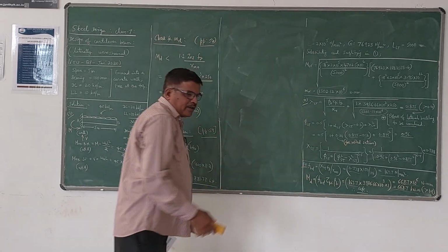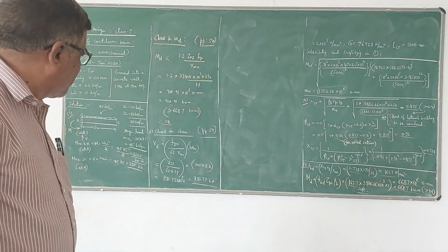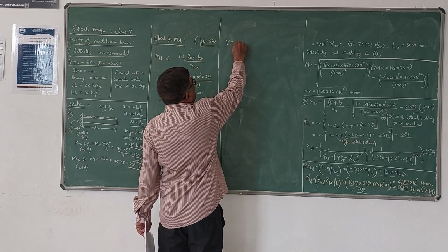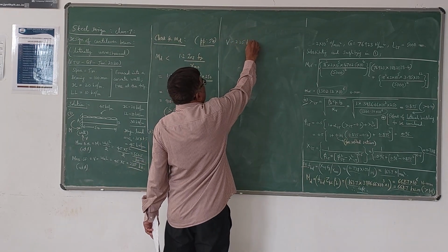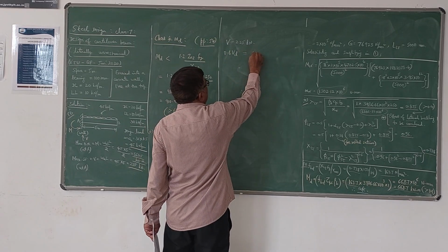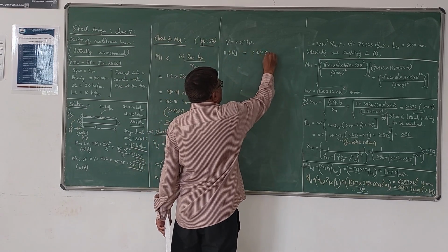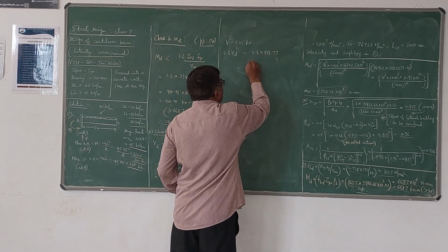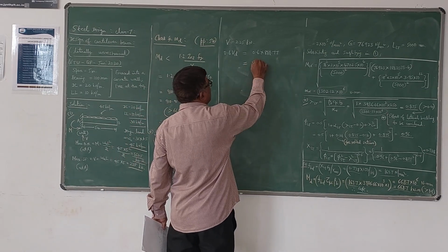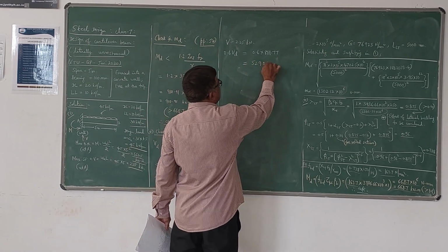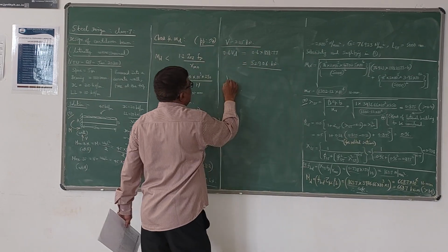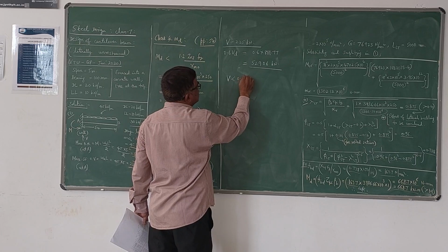So here V is 225. You know that here maximum shear force is 225 kilonewton. Now you take 0.6 times Vd. 0.6 times Vd is 0.6 into 881.77, which is nothing but 529.06 kilonewton. Now you can observe that this V is less than 0.6 times Vd.